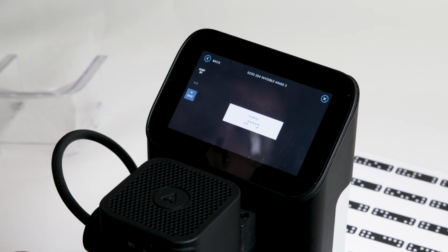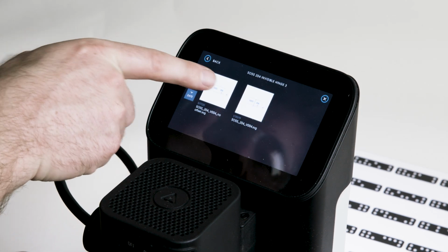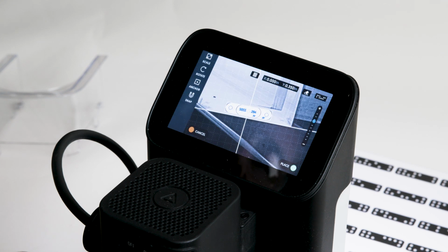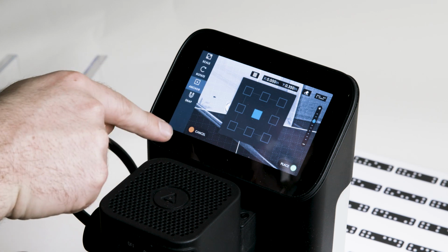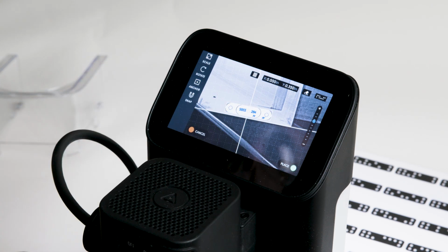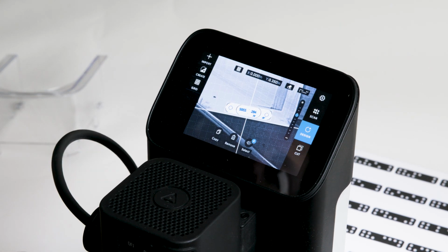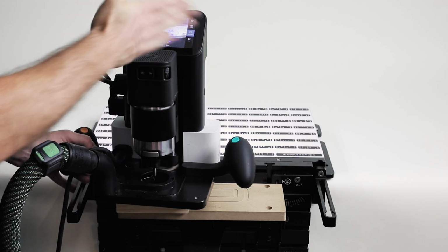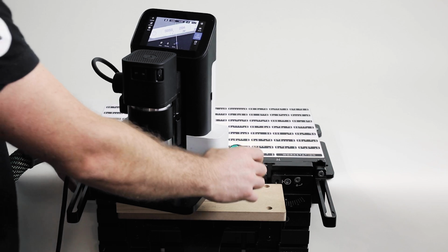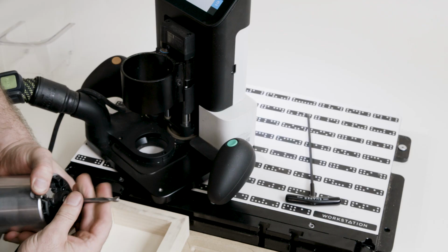Which means when I go import, I'm actually looking at my sauce hinge file. I'll load it in, and I'm using the anchor point that is centered. So accept that, place. So we're now super confident that this is centered between those two edges within the stock, and there's no orientation issues. It's always going to be exactly parallel.